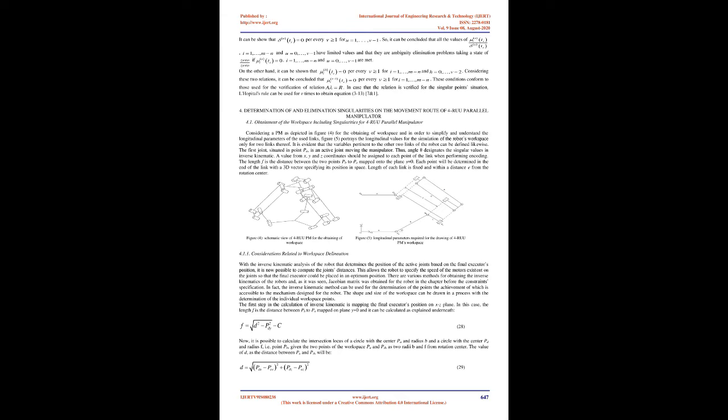3.3 Implementation of the limit method for removing singularities from the robot's workspace. To remove the singular points from the workspace, theorem number 6 of the limit concept was applied according to Ozdemir 70. Based on the theorem, if the number of equations required for the constraint exceeds that of the problem's unknowns, n, the following limit can be defined, where λ denotes eigenvalues of the Jacobian matrix, t is the time parameter and ts indicates the sampled instant.